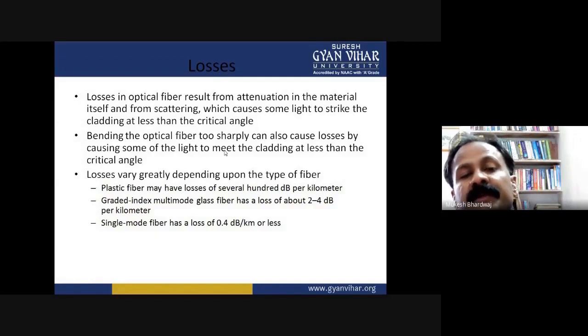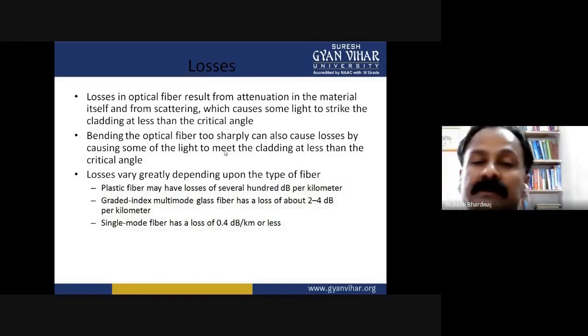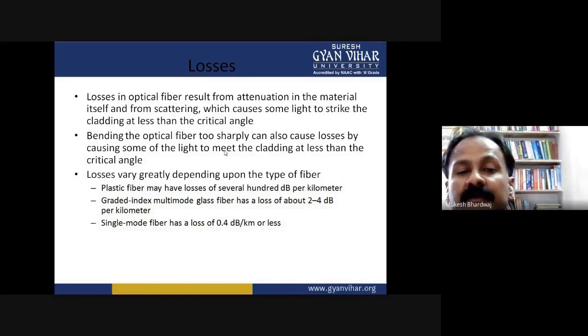This vapor axial deposition method was developed in 1977 by Japanese scientists. Depositing the glass particles, which were obtained from reaction among gases in a heated zone, occurs at the bottom end of the target or seed or rod that rotates and moves upward. This deposition forms a porous preform, the upper end of which is heated in the ring furnace to produce a glass preform.